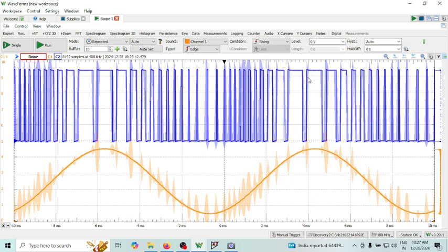So these are a few variations that you are supposed to do in square wave generation. One is without any control voltage: what is the on time, off time, duty cycle. Duty cycle is always more than 50%. Then you apply control voltage and see what VTH and VTL are, whether equal to the external voltage and half of the external voltage. That is the second variation. The third variation is to connect a diode bypassing resistor R2, the discharging resistor, during charging time.